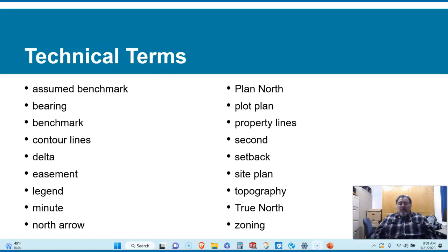So when you're establishing where your building is going to be placed, minimum setbacks are something that one would take into consideration, because building code says that you cannot be right up against the property unless you have a special reason or special condition to be able to do that, an exception to that rule.